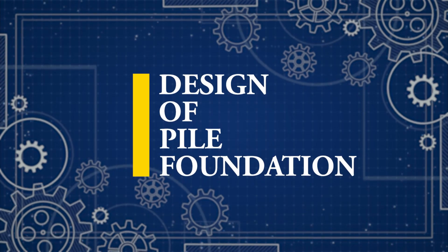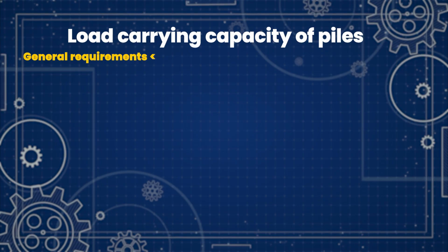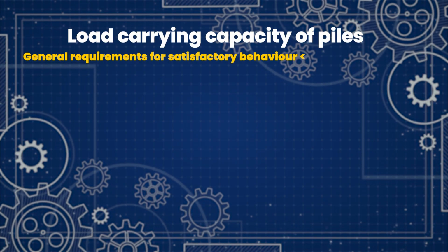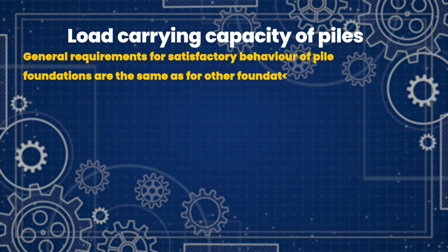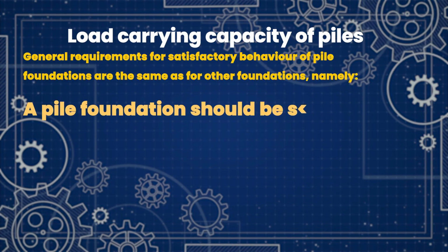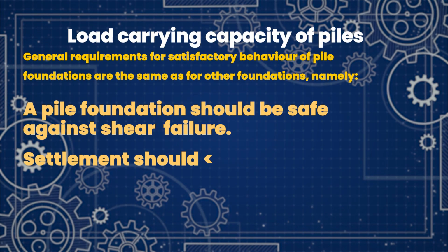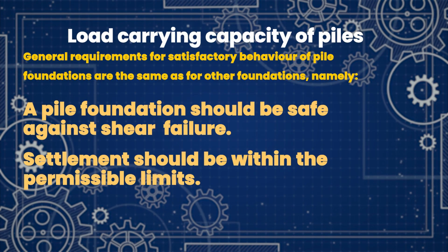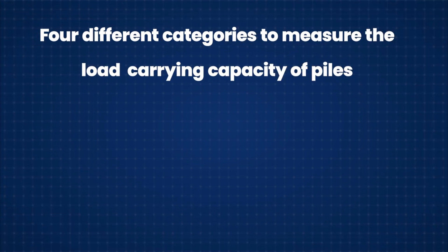Today I am going to discuss an important topic, that is design of pile foundation. Firstly, we should understand that the behavior of the pile foundation is the same as other foundations. So, the objective of this pile design is to be safe against shear failure, and the settlement should be within permissible limit. There are 4 different methods to calculate the pile capacity.